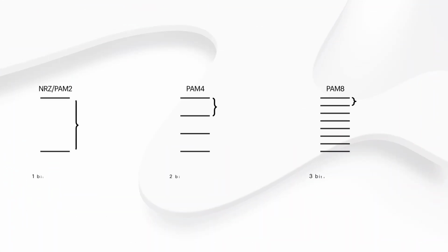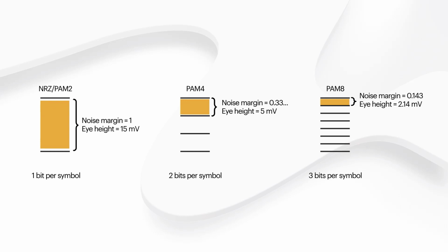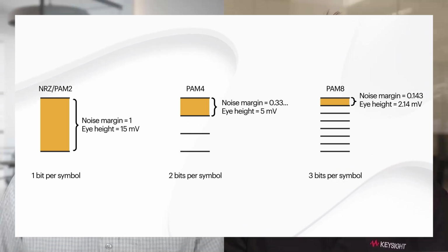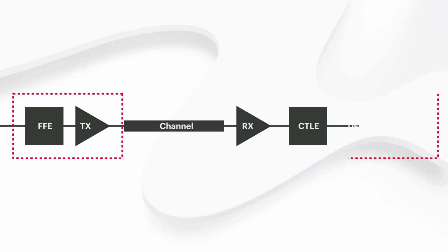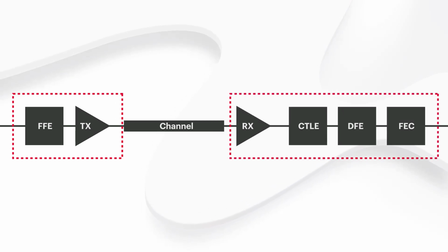Yes, right. It's really both those things together. Smaller signal height and more voltage levels equals a lot less spacing between our levels. But the other part is the eyes closing due to the channel bandwidth, and so there's a variety of equalization techniques used to try to recover that eye, to open that eye back up.